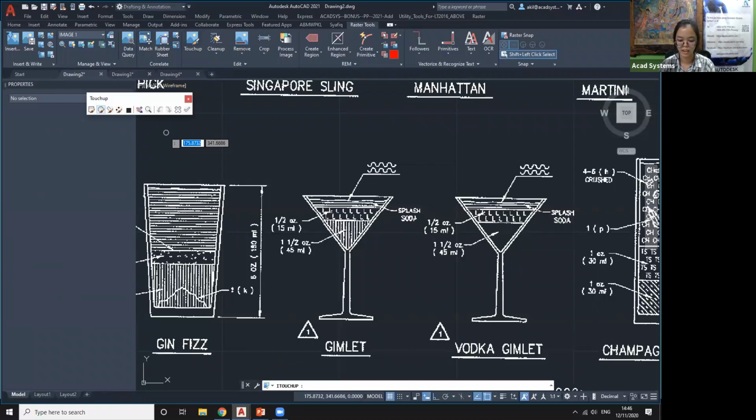So the shape of the brush can be defined by the tools on the left side of the toolbar. So I will be selecting the round brush. And then the angle of the brush is this one, the third one. While the size of the brush can be changed by clicking this button. This will let you define the size by either dragging a window or by entering a number. So I will just click this size.